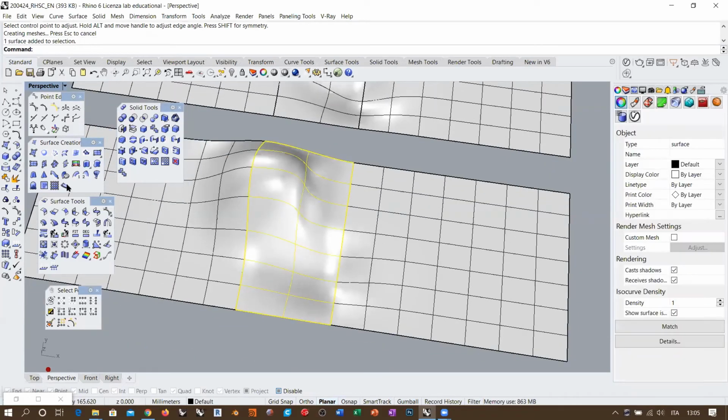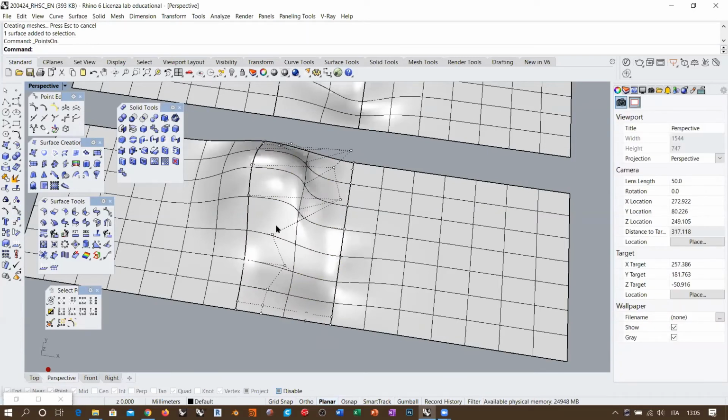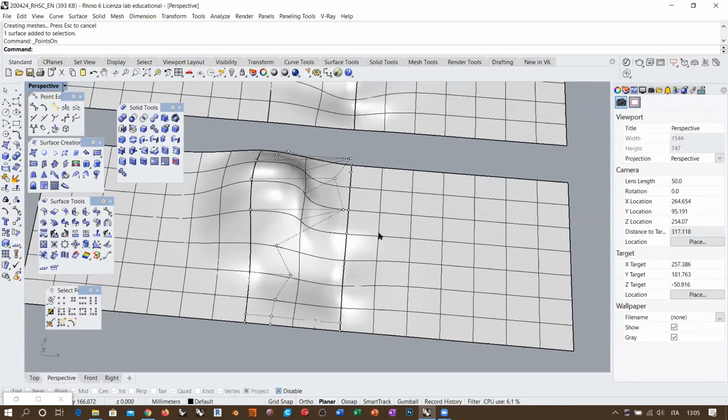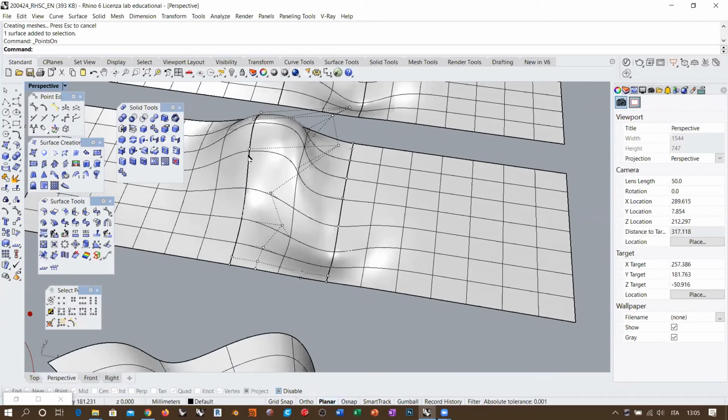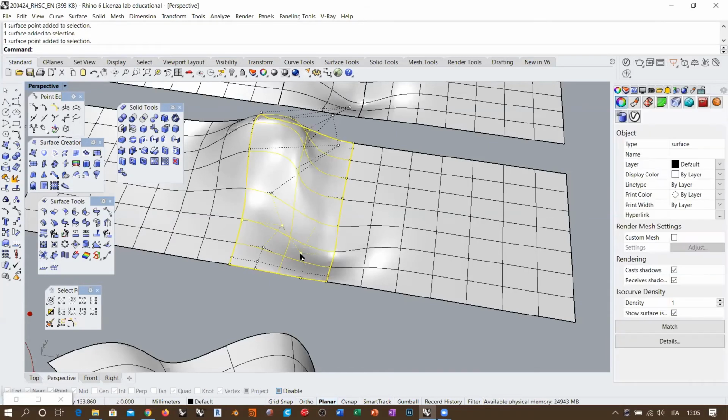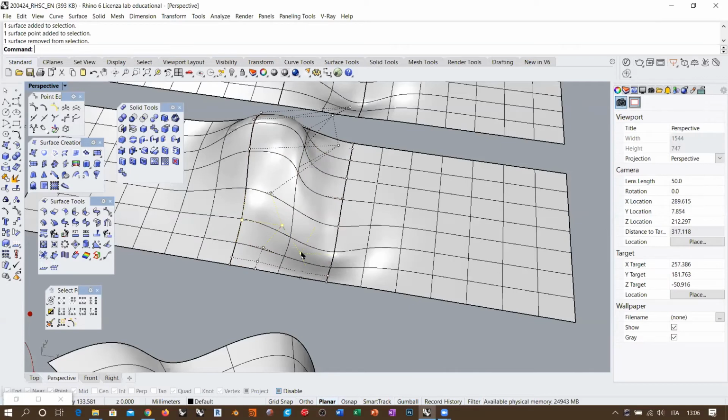But you have a surface, degree 3, with just 4 control points in this direction. So if you want curvature continuity, for example, along edge 1, which is here on the left, you need one control point here, another control point, and also the third control point here must be used in order to create curvature continuity along edge 1. If you do this, there is no possibility that you have curvature continuity along edge 2, because you would need another 2 control points that you don't have, okay?